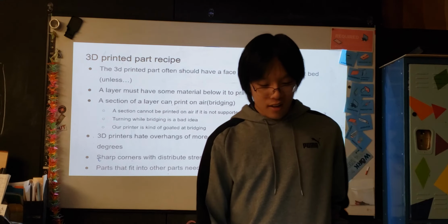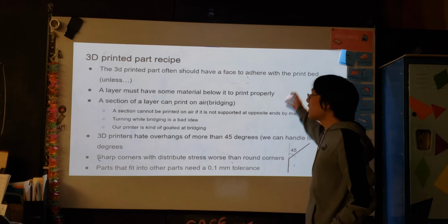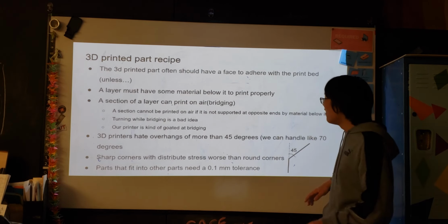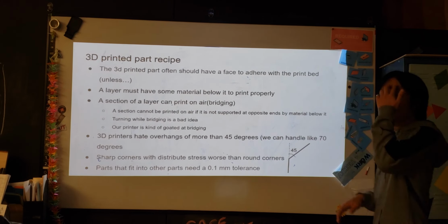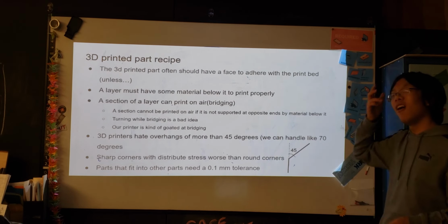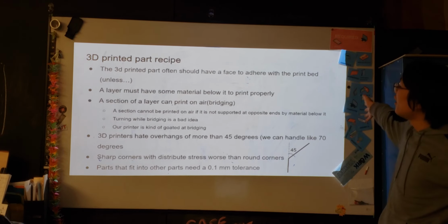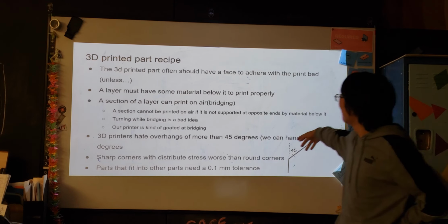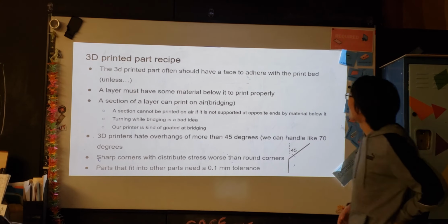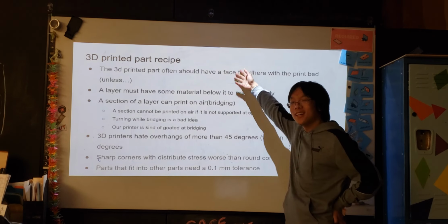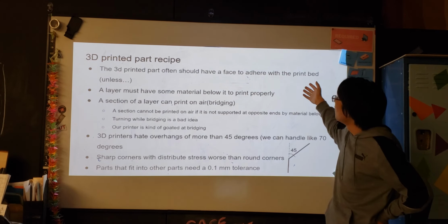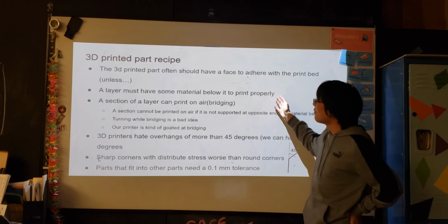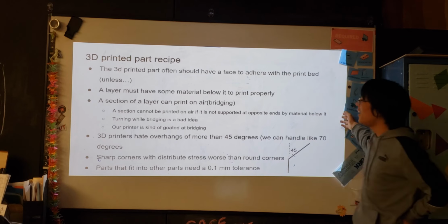So this is a set of rules to cook up a strong design. Your 3D printed part should adhere to the print bed, unless, I'll get to that. It should always have a face to adhere. A layer must have some material below to print properly. It's pretty self-explanatory.